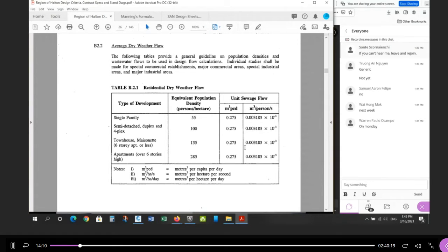And once you learn how to read the standard, we worked in CDA. I taught you a little bit about the town of Richmond Hill. When you navigate the town of Milton standards, you'll see a lot of similarities, right? The details are a little different, but the kind of information you're looking for is very much the same. What's the minimum slope? What's the maximum slope? What are the K values for the roads? What's the curb return radius, and so on. So these are pieces of information that you need, and then depending on which municipality or region you're working in, the details may be a little different, right? But certainly if you can navigate the standards for one municipality or one regional government, at least you know what's in them.